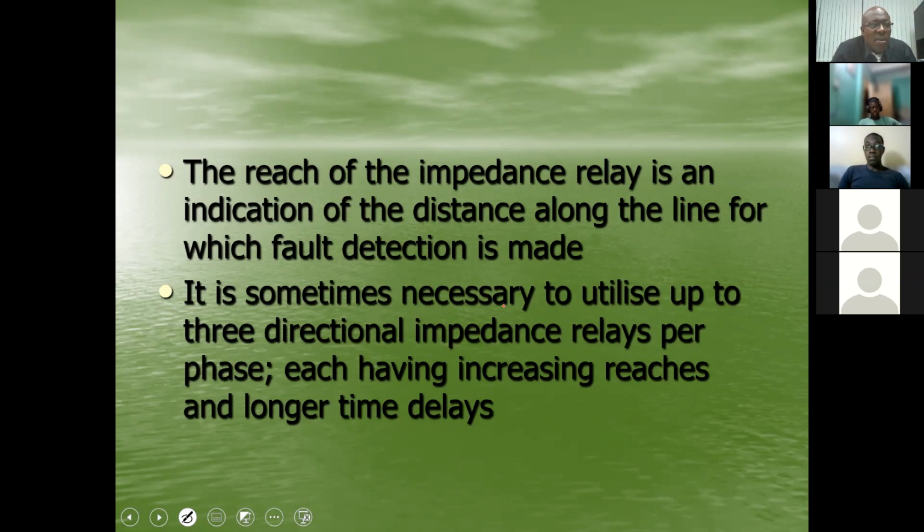Good? With your static relay, you have 1 relay, and you'll get the input from all 3 phases. As a matter of fact, some of those relays give you the option of not only distance, but overcurrent protection. So the cost for your relays is therefore much less.